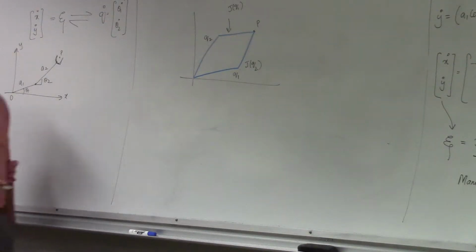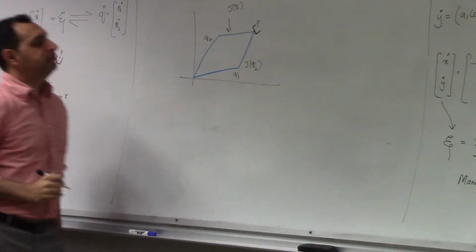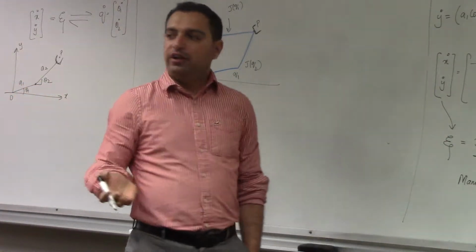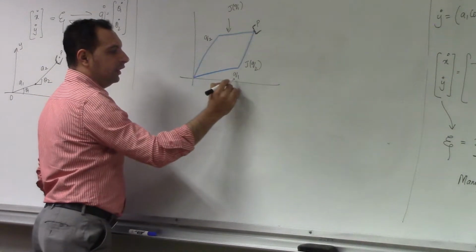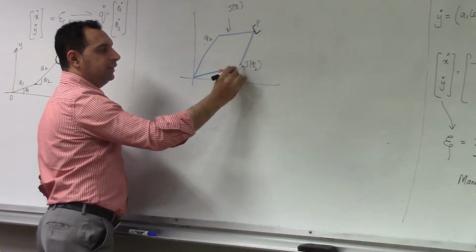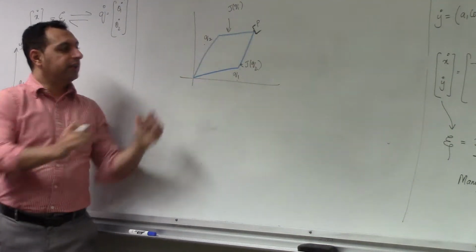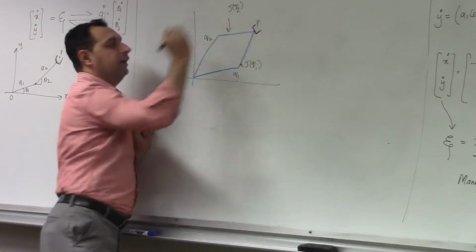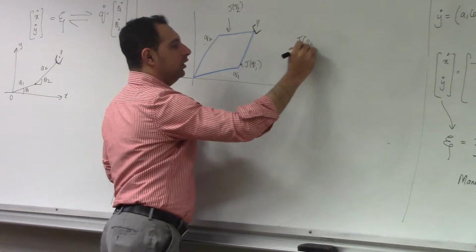Because what I'm trying to explain is, you're reaching the same point in space, right? You're reaching the same point because this has 2 solutions. If you go to a more complex manipulator, you will have 4 or 5 postures in which you can reach the same point. So in this case, Q1 is one posture, Q2 is another posture. Now, if I calculate the Jacobian here, and if I find the Jacobian here, obviously, here I have to use these joint angles, and here I have to use these joint angles. Will J of Q1 and J of Q2 be equal or different?